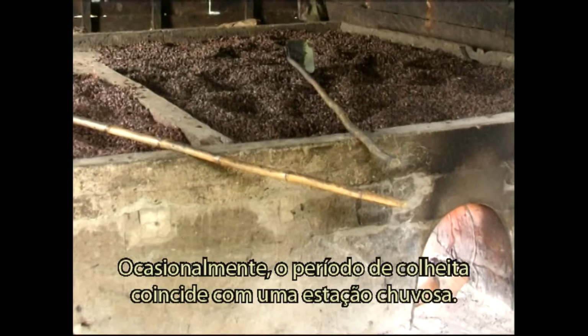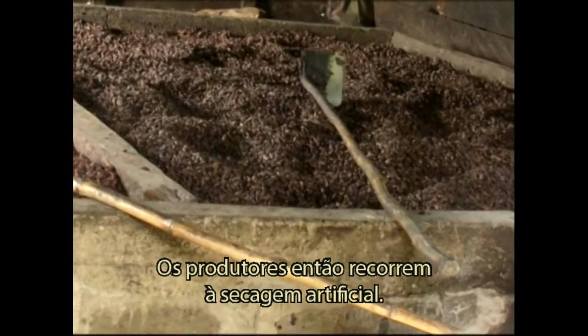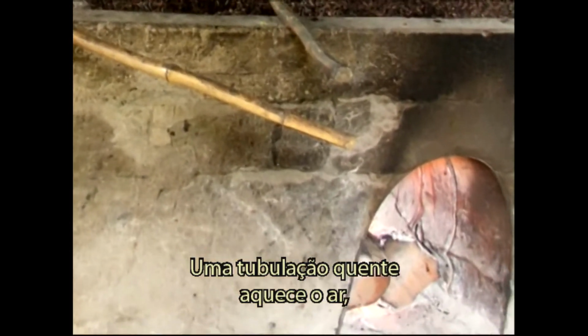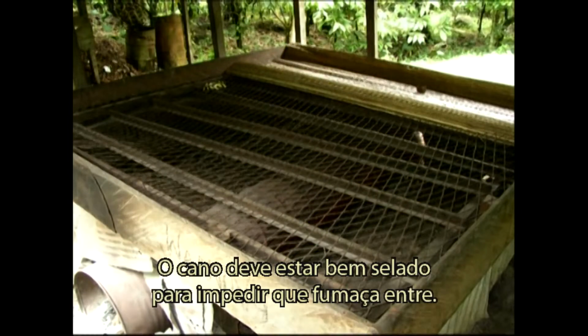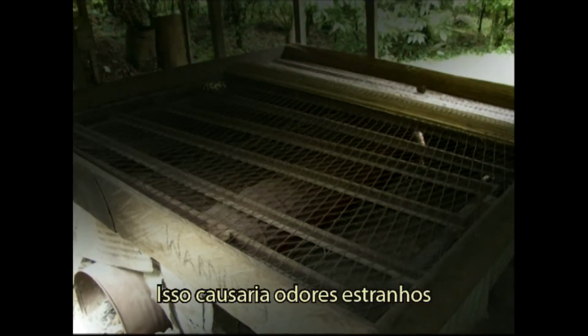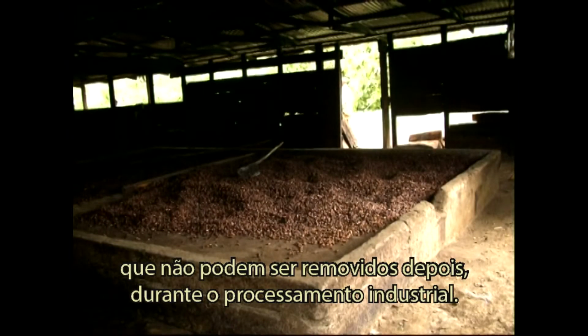Occasionally, the harvesting period falls in a rainy season. Farmers then have to resort to artificial drying. A hot pipe warms the surrounding air, which passes through a drying mat and the wet beans. The pipe should be well sealed to prevent smoke from leaking. This creates very bad off smells that can't be removed later during industrial processing.